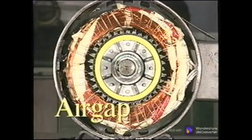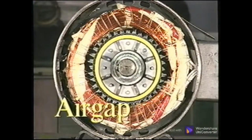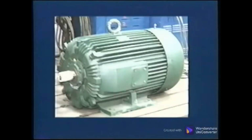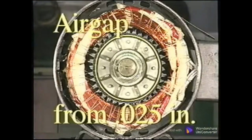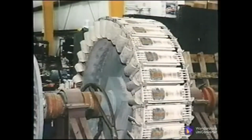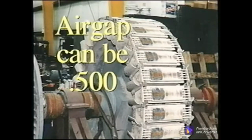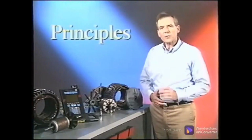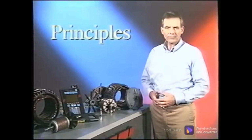The air gap between the stator and the rotor must be the minimum distance that still allows for thermal expansion of the rotor and the flexing of the stator. Depending on the motor size, typical air gaps range from 25 thousandths of an inch to 100 thousandths. In very large motors, the air gap can be as much as 500 thousandths. Now that we've seen the components that make up a typical motor, let's take a look at the principles that cause a motor to work.